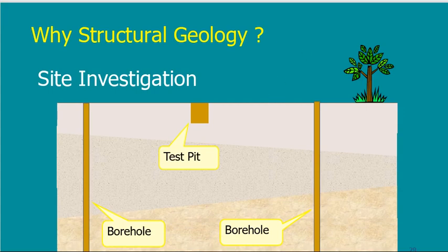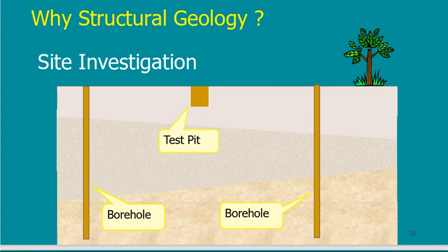Now we are going to go to the most important part of the lecture, which is the link. We studied geology. Now we want to know how to use this geology in geotechnical engineering. As you remember in our previous lecture, when we were studying the introduction to geotechnical engineering, we said that to know the layers, we do boreholes, or we do test pits. Test pits are very shallow.